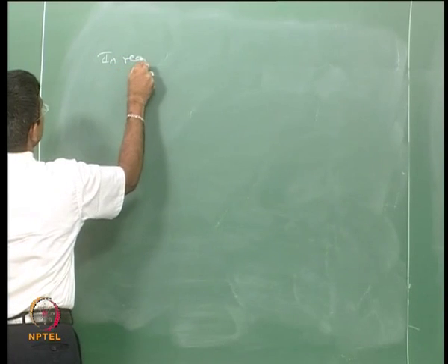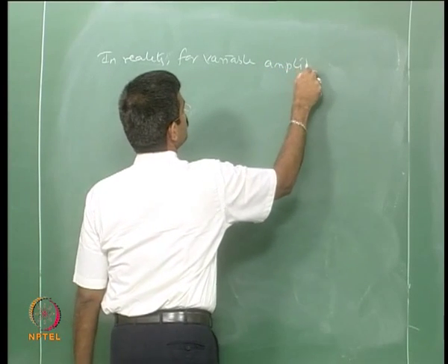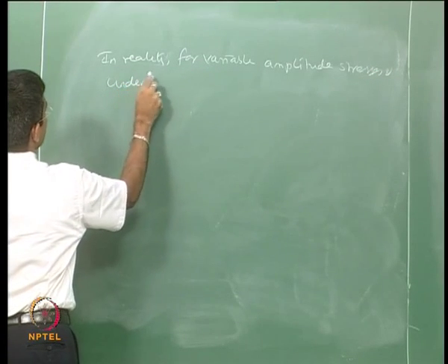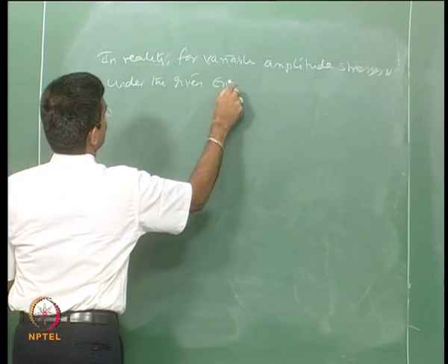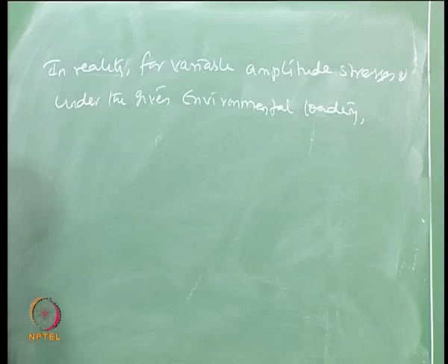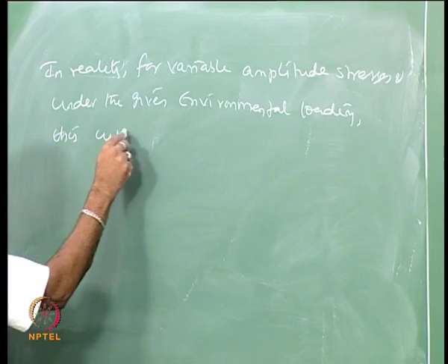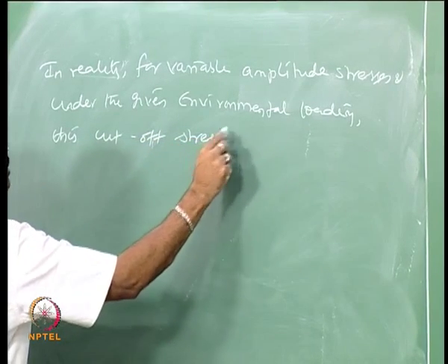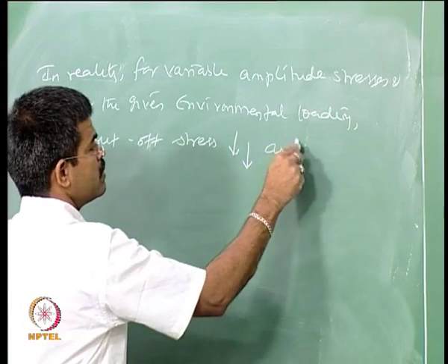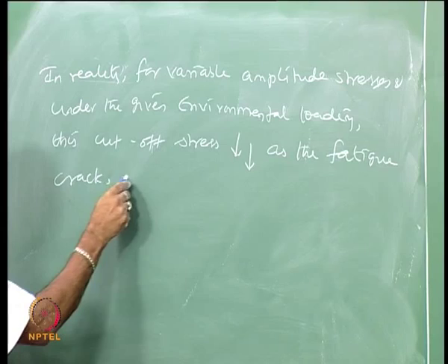Now, in reality, for variable amplitude stresses and under the given environmental loading, this cutoff stress decreases as the fatigue crack grows.